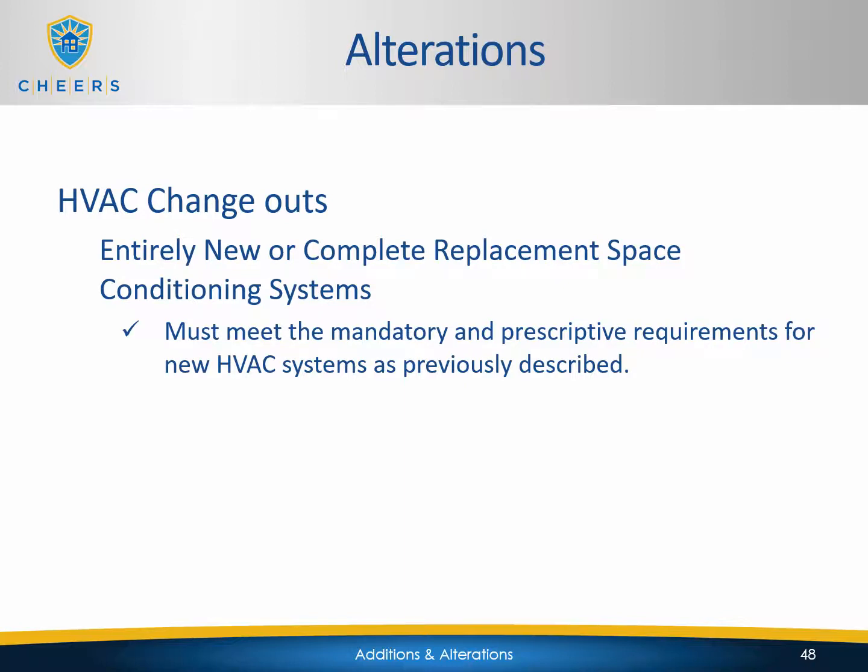It must meet the mandatory and prescriptive requirements for new HVAC systems as previously described. Back in the Title 24 overview, we went through those different ones. Depending on the type of alteration that's done, it could be duct leakage testing, fan watt draw, airflow, return duct design, and air filter design. Prescriptive side, refrigerant charge. So there is the potential for several HERS inspections to be required, along with the mandatory measures for equipment efficiencies and duct R values. All those items do come into play on these systems.